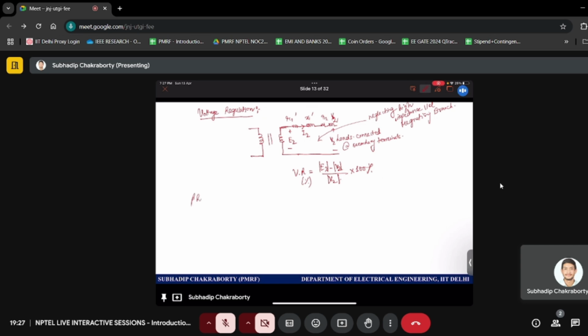And then if we draw the phasor diagram, you can see that if this is V2 and I get a lagging power factor at the load end, which is of, let's say, theta, then V2 plus this drops, so I can say I2 R equivalent, and then j I2 X equivalent, if all these are X equivalent or R equivalent, we can write, then this much is the actual E2.